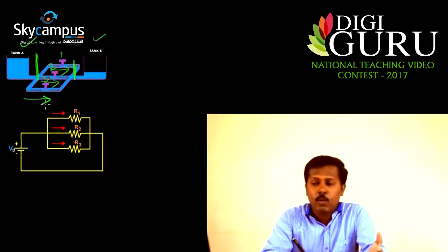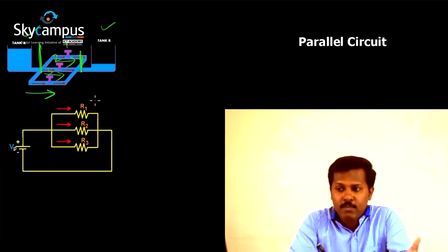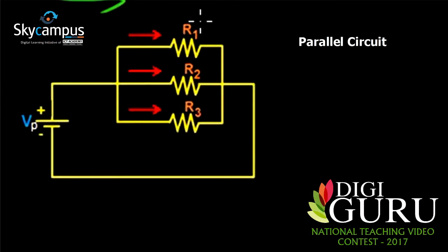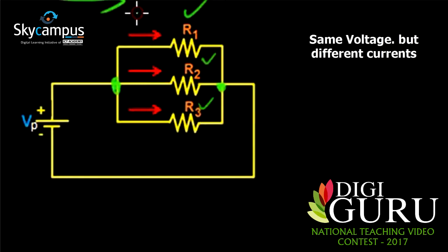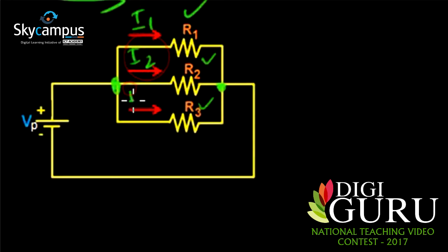A similar kind of circuit can be seen in electronic circuits also. That kind of circuit is known as a parallel circuit. You can see that there is a circuit with a potential difference, a battery connected here, and it splits into three paths, and in each path you can see resistors R1, R2 and R3. These kinds of connections are known as parallel connections. The three branches are connected to a common point, so the potential difference across the resistors is the same. There are three currents flowing through these three different branches, let us say I1, I2 and I3.